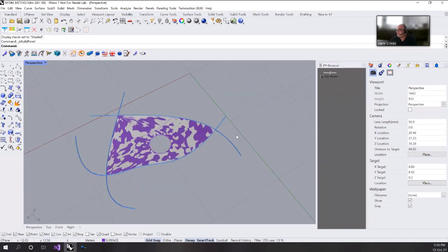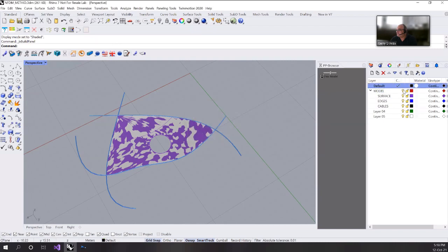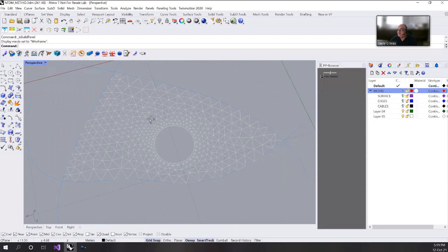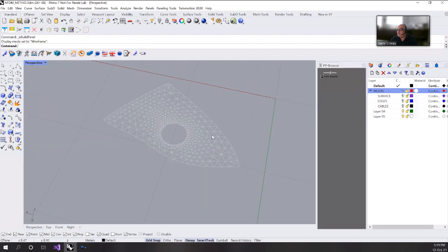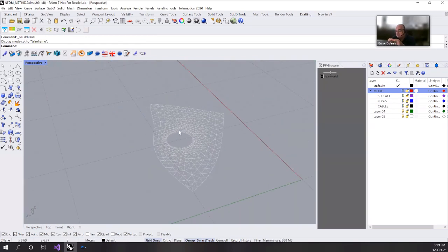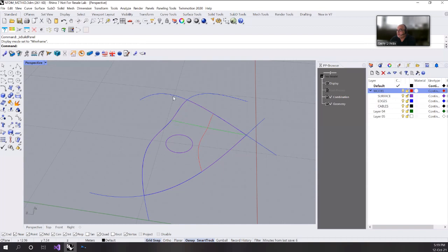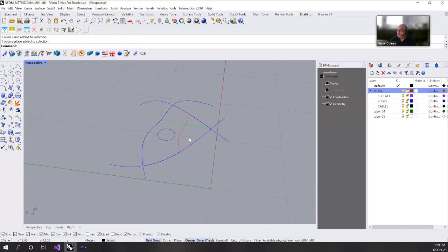So if I hide here, yeah, this is my finite element model. So, for example, I can use this. I can apply loads and get results out of this object. So clearly, what happens? This is my finite element model, and this is my CAD model. In my CAD model, I am using NURBS curves and NURBS surfaces, and these are converted to a finite element model by Falco.